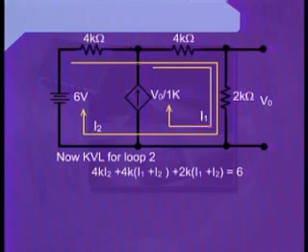As we complete this term as well, we reach at the independent voltage source, and as we reach there, we can see that the negative terminal of the voltage independent source is towards us. Therefore, we can write either way, that is -6, or we can equate all these three terms to 6.